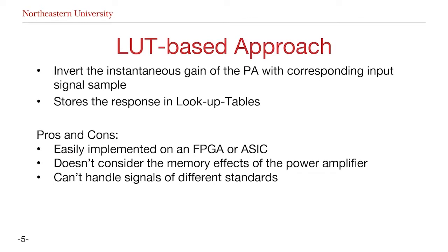Another approach for digital pre-distortion, but in a relatively easier way of doing it, is to use the lookup table-based system. For each sample of the input signal, the system will pre-distort the signal solely based on the gain and the phase of the current signal samples.